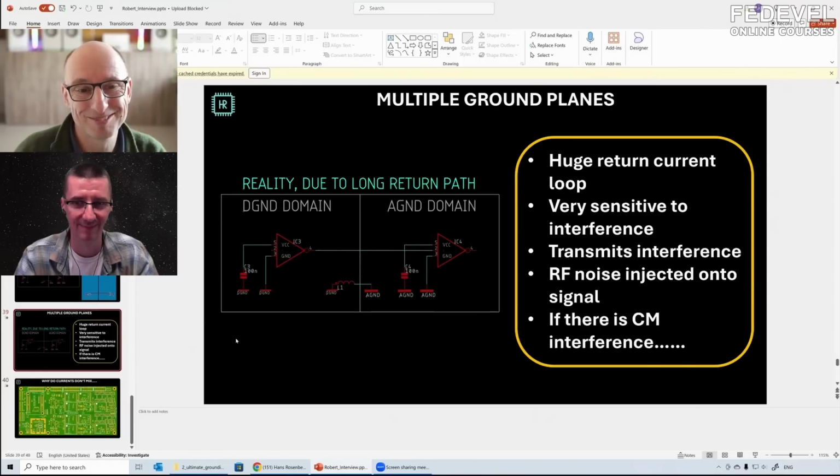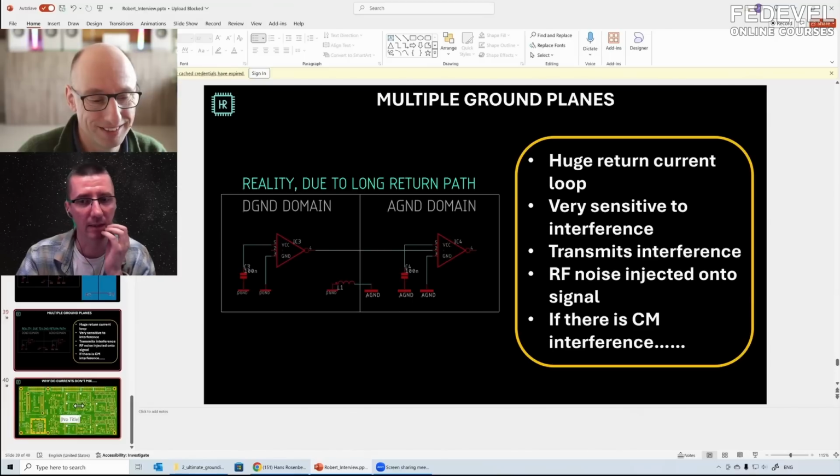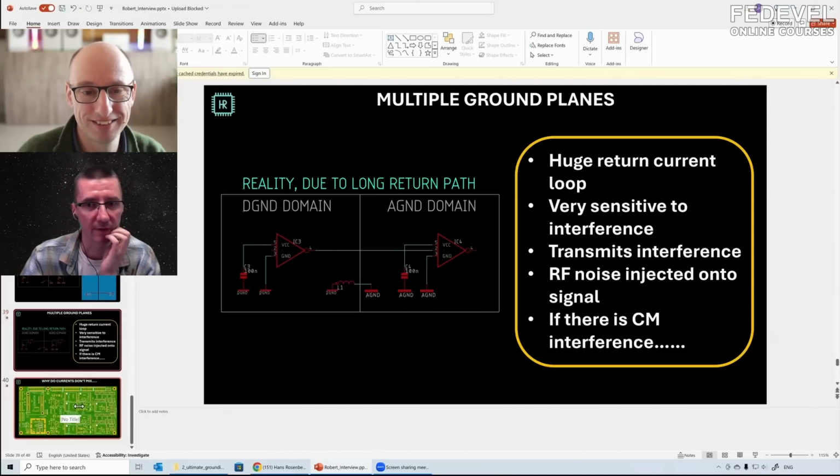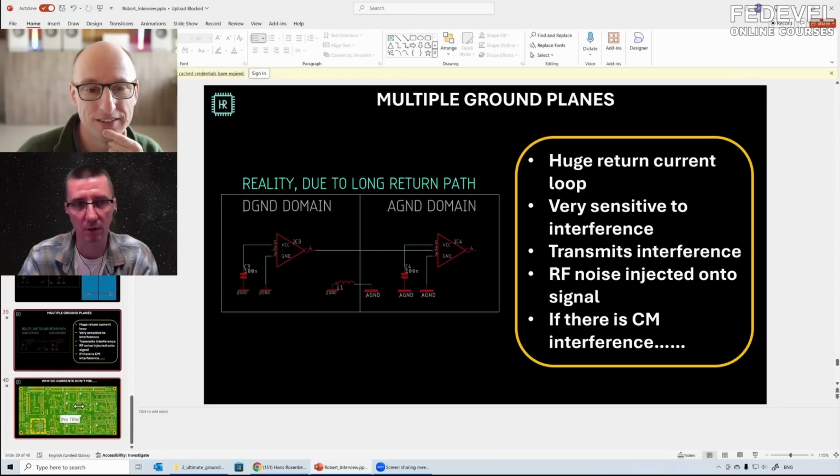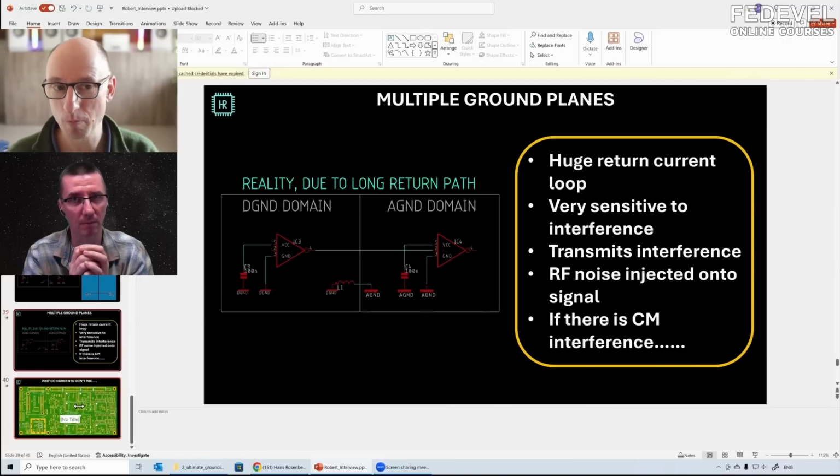I agree. I would like to mention that even high current doesn't always have to be a problem, because motherboards can have tens or even hundreds of amps in the digital part, but the key is you place the power supplies extremely close to the power pins, so it doesn't spread all over the board.